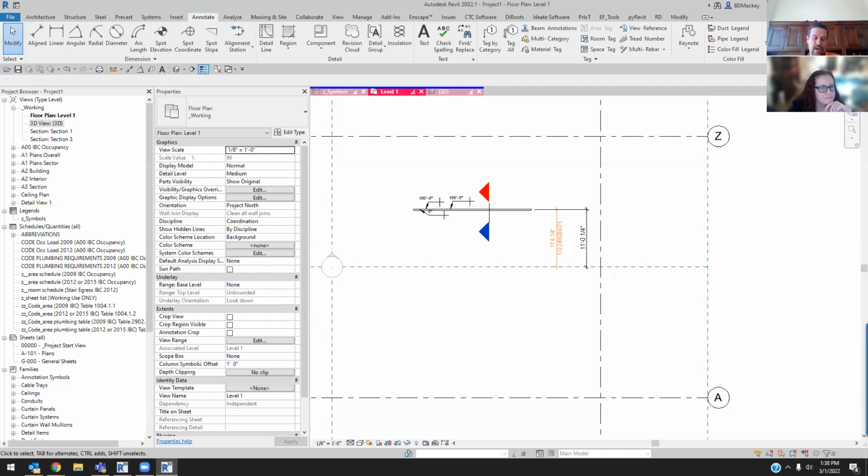This is why I'm very careful, assuming this is fake Jason on a BIM 360 project. All of my BIM 360 projects are set up so a user goes in and we link to their live Revit models, so we're not going through the whole publish and consume. We link directly to the folder they work in. I always say it's almost live, because if I hit synchronize, that is not going to trigger the architectural model or the structural or any other discipline's model to automatically start reloading that link. I could be in the middle of a command, it's not going to do that.